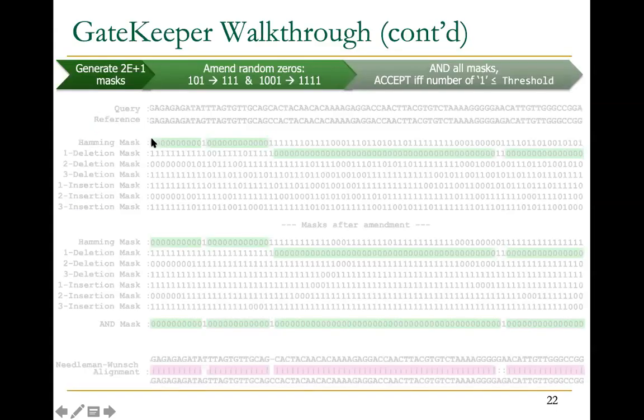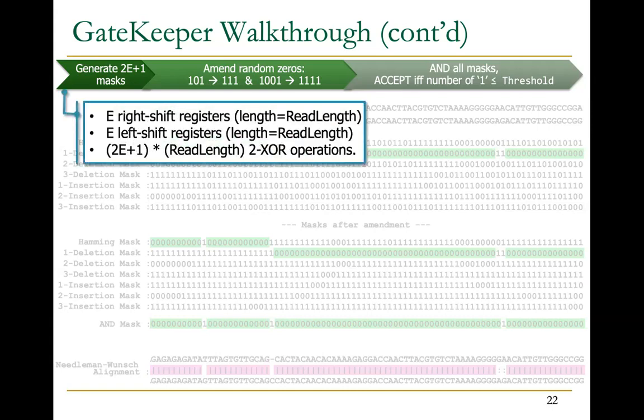All right, now how about the hardware acceleration, or how we realize this algorithm in logic or in Verilog, for example? First, to generate the vectors, how many operations do you need? For the Hamming distance, you need just XOR, right? And how many of these XOR operations, assuming it's a 2-input, 1-output XOR gate, do you need? You need basically as many as the sequence length. So if the sequence length is 100, then you need 100 of these gates, right? So 1 character from one sequence, another character from the other sequence, and you get 1 bit out of this.